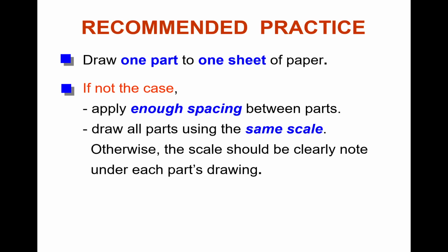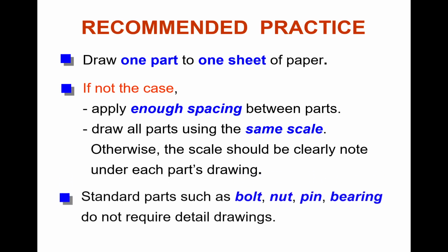Okay, otherwise if you want to use a different scale for different parts, the scale should be clearly noted under each part's drawing. And then standard parts such as bolt, nut, pin, bearing do not require detailed drawings. Okay, for these you don't need a detailed drawing because as we know, standard parts, we can get the specs from the manufacturer. It's easy, they already have their standard specs. So no need for detailed drawing.